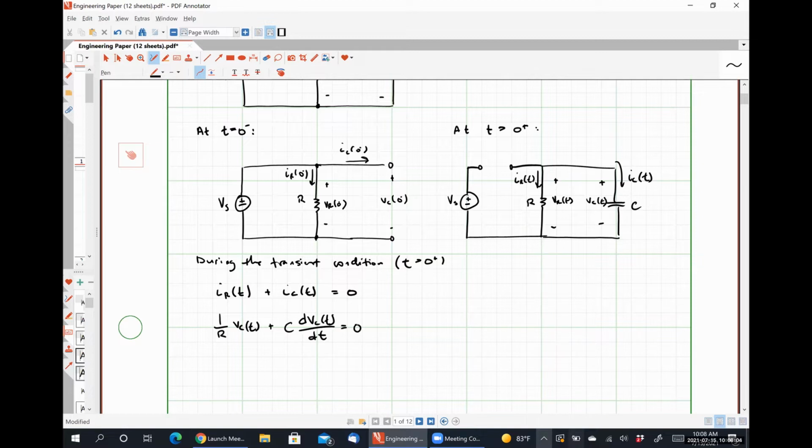So when we dealt with our inductor problems on Tuesday, we guessed that our current waveform was of the form A e^(st), and we'll do the same here because we have the same type of equation, so it seems reasonable that it'll have a similar solution.